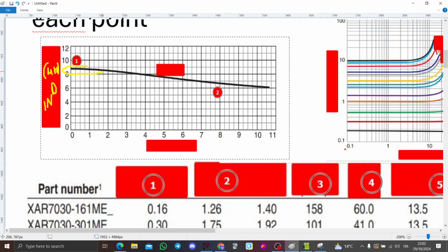And this is the maximum value that you can achieve when there is low current. This is a typical graph of our inductors, because when they reach a higher value of current, in amps, so this is the load current, once they reach the limit, they lose more or less 20 to 30% of their inductor value. And as you can see, it matches the description.